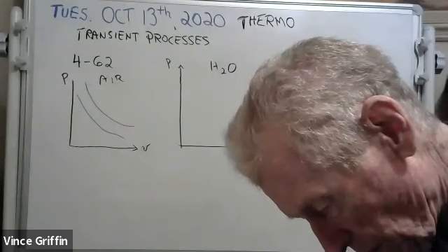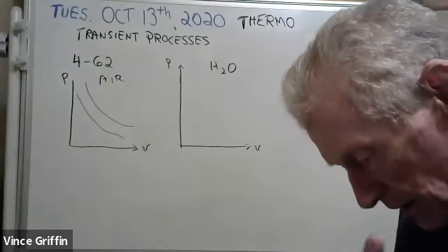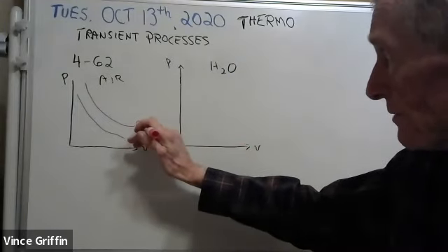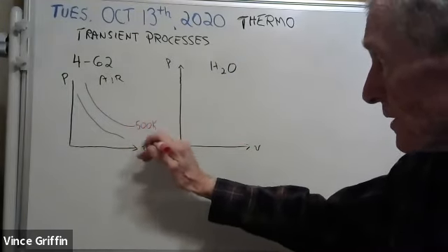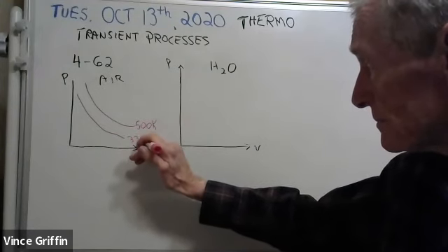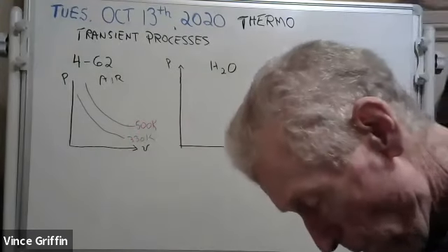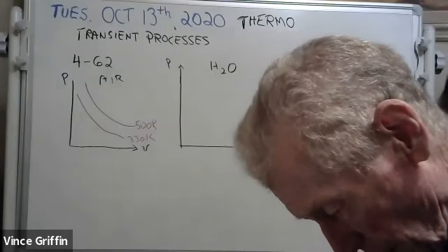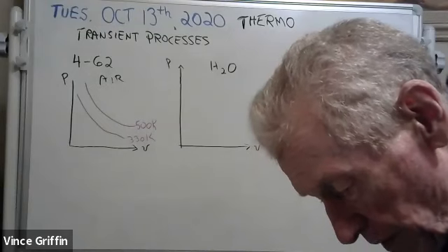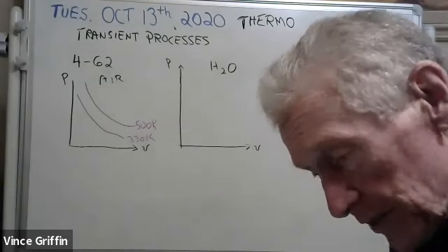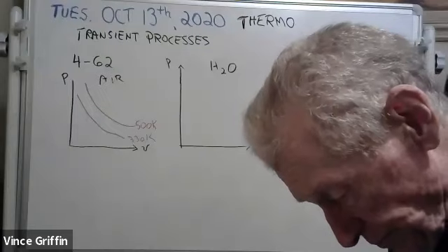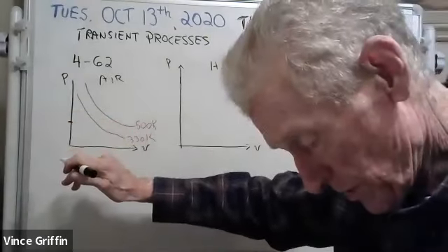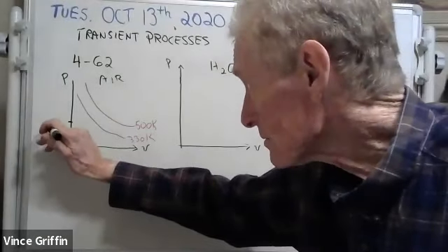You got air coming in at 500 K and it leaves at 330 K. So you got 500 and 330 K. And we've learned that heat exchangers are isobaric. So this is occurring at 200 kilopascal.